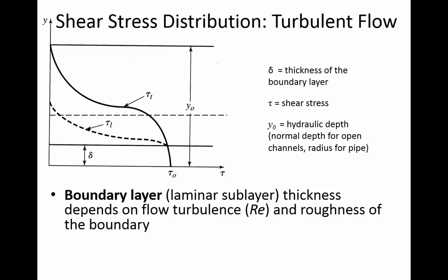So let's go back to when velocity was low. If velocity is low, that means it's slow in the center, but it's also really slow around the edge. So there's some section of the pipe near the edge where the velocity is really slow, and the Reynolds number in there might be less than 2,000 even. You could have laminar conditions in that boundary layer.